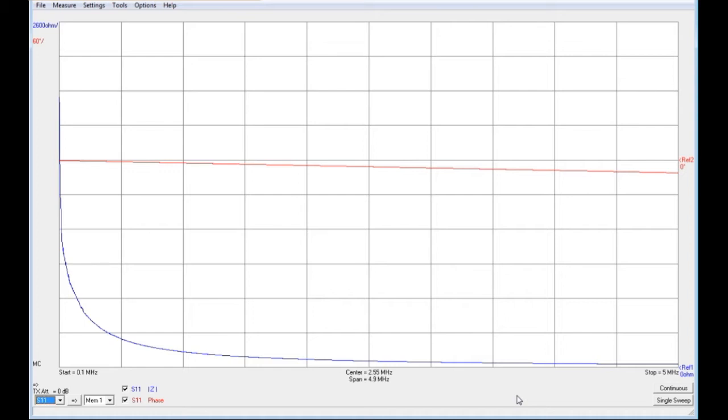Okay, back to the software. So the first consideration that we need to make here is what is the frequency span that we're going to measure. Now, as I spoke in a previous video, most Tesla coils that I've ever worked with, or of this nature, or if you're working in the HF ham radio band, then the band of interest really goes as low as 30 kilohertz and up to around about 30 megahertz. So that's really the band of most interest.